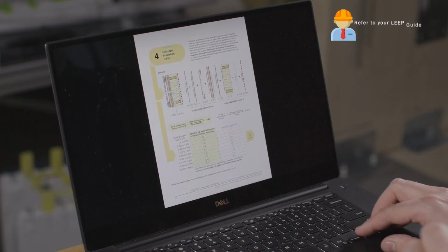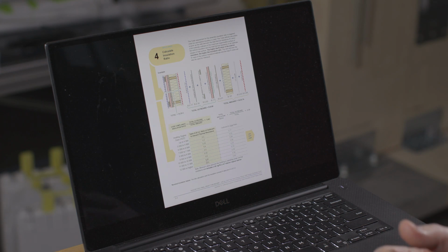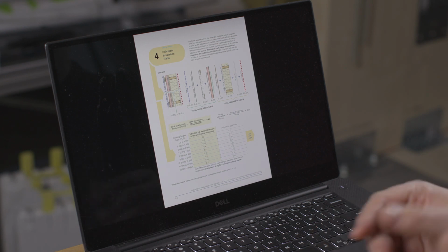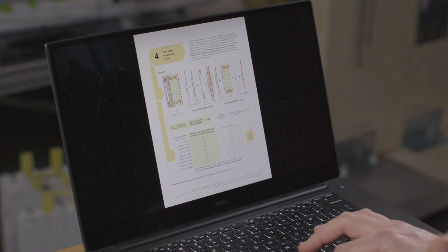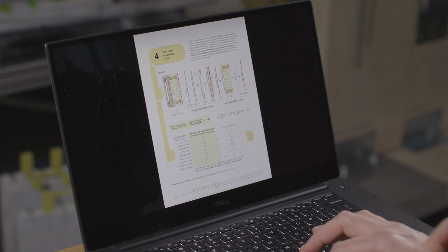Okay, so we've selected our insulation based on permeance. We're then going to look at the insulation ratio. The reason we're looking at the insulation ratio is we want to look at the outboard to cavity insulation ratio. And if you run through the calculation here, what you're looking for is to see how much exterior insulation you have, and if you can, get enough exterior insulation that you potentially don't need a vapor barrier on the inside.